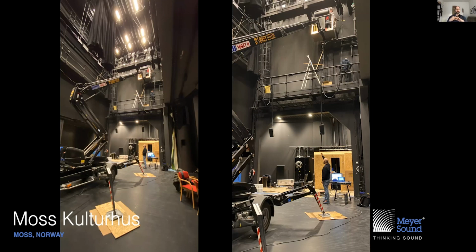What's commonly found on stage is a flutter echo that you might get from the two sidewalls over here. That's an echo that goes back and forth. And in some cases, the upstage back wall can also create a reflection that goes all the way back into the audience. So with all this acoustic treatment, we're able to really neutralize those reflections. And that way, Constellation can reintroduce those early reflections. Now we have a lot more control, as well as adding the reverberation on top of that.